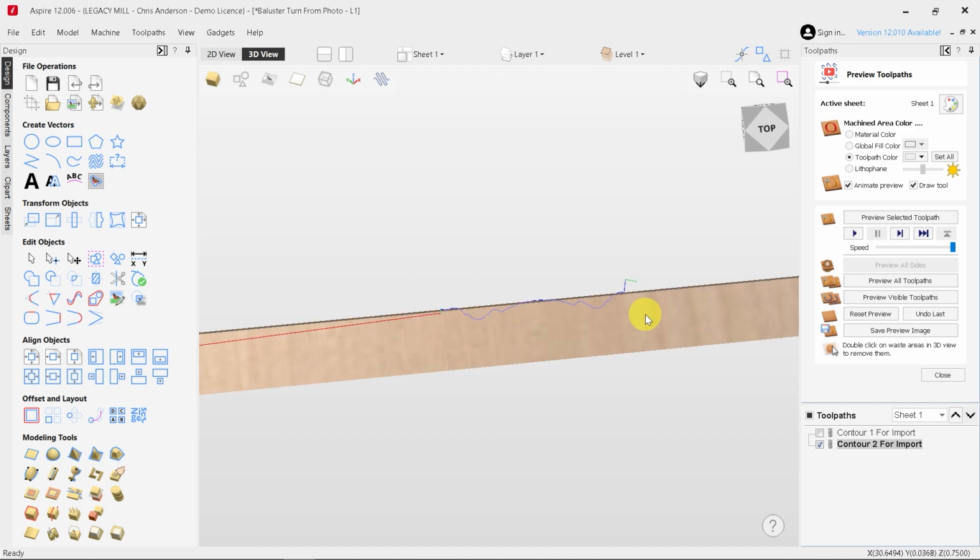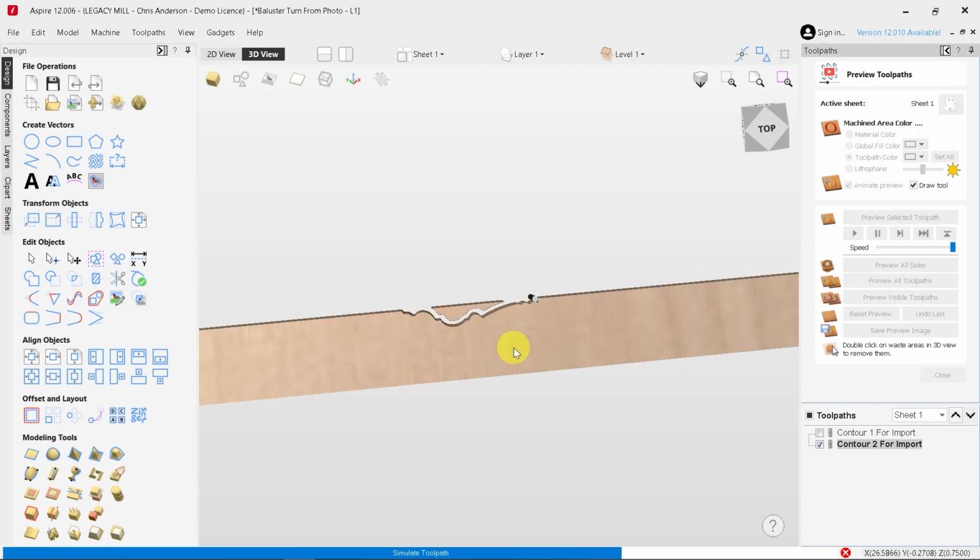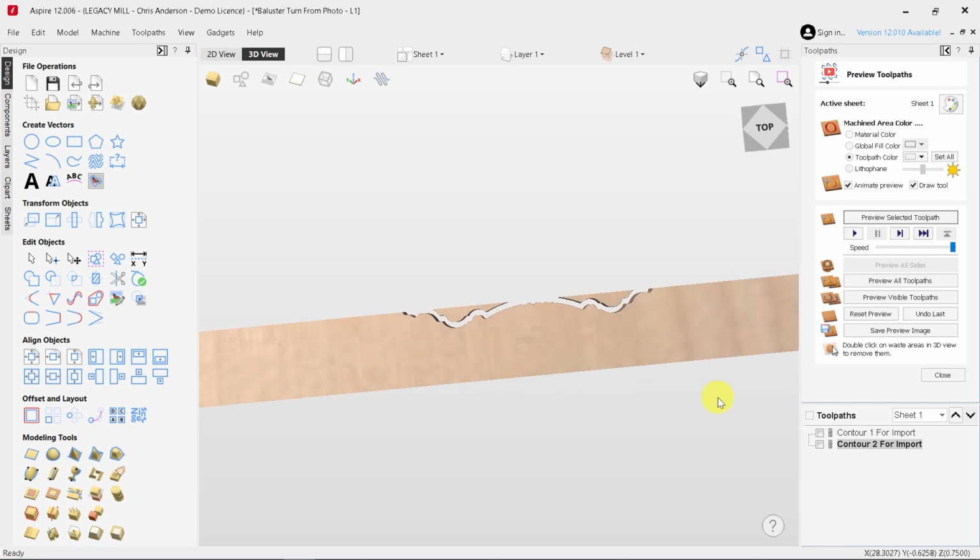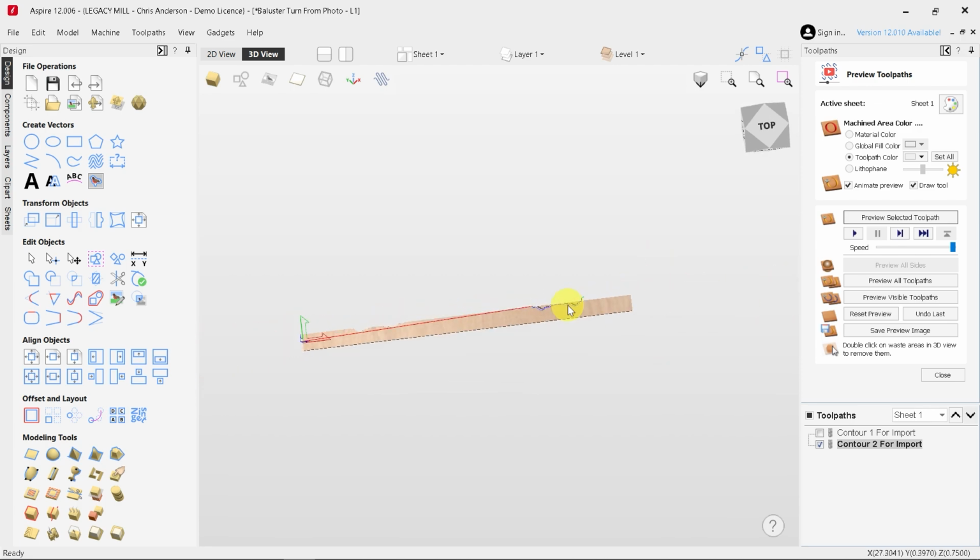Okay, we can go to this side and preview that one. And yeah, it cuts from left to right exactly how we want it to. You can see that the cutter is going to lift up, giving us that chamfer along the corners, as it's constantly turning from a round to a square section. So these look great. And again, these are just 3-axis functions.